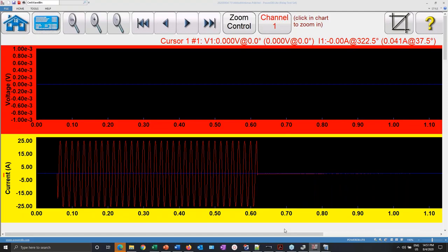So you take the result. I guess I'm describing a process that would be familiar for many, but there are also other uses for this, which is doing end-to-end testing using this type of file. You can generate the faults in a more realistic form than this one that I have right here, with a DC component, with harmonics, with other elements incorporated. What I did right here was I created a fault, played it into the relay, and took it from the relay and back into the realm of the RTMS.